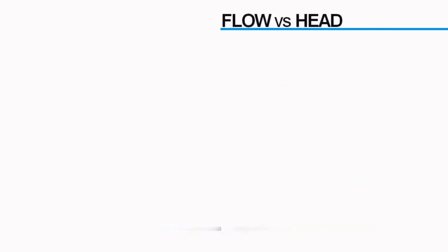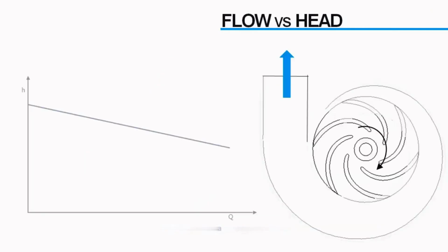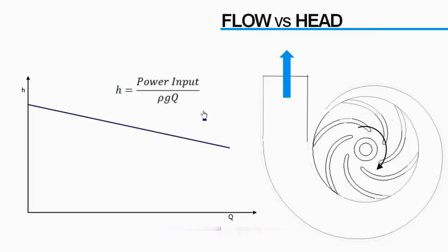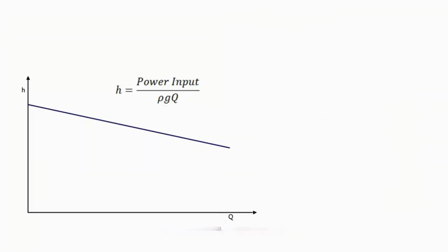We had discussed that energy head developed by backward curve pump decreases linearly with flow. But this is theoretically maximum energy head possible, obtained assuming whole shaft power input got transformed to fluid energy. This is true only for ideal cases. In practice, there will be lots of energy losses associated with pump flow.